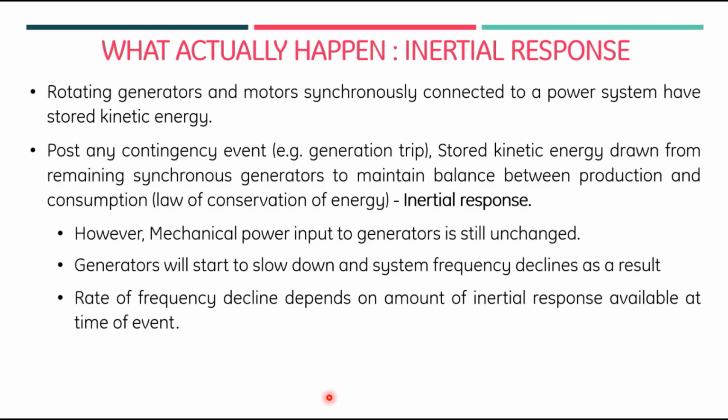And then as you synchronize this, let us say it is a 1000 megawatt machine, which has a capacity of 1000 megawatt. It may take around 30 or 40 megawatt to run that much kinetic energy in the machine, to first run at 1500 rpm without producing any electrical energy. This 40 megawatt is just to run the machine at that particular speed. So whatever kinetic energy is stored is extra over there.